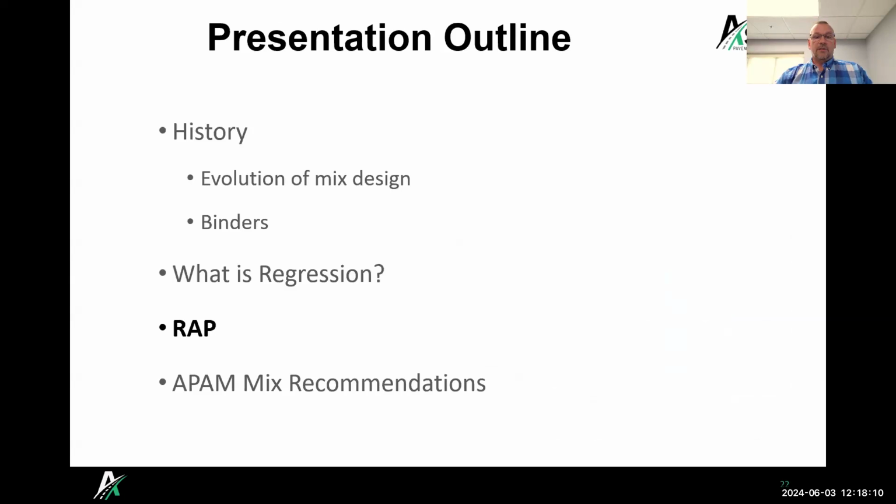So next I want to talk a little bit about RAP. Why do we want to recycle RAP into mixes? Really, it's its best and highest use. You can see the same or better performance as virgin mixes. Recycling reduces the demand for new materials, reduces our carbon footprint, and it really contains valuable materials. People like to use RAP for gravel applications, but you're really not using that for its best and highest use because you're not reusing that liquid asphalt in your new mix.